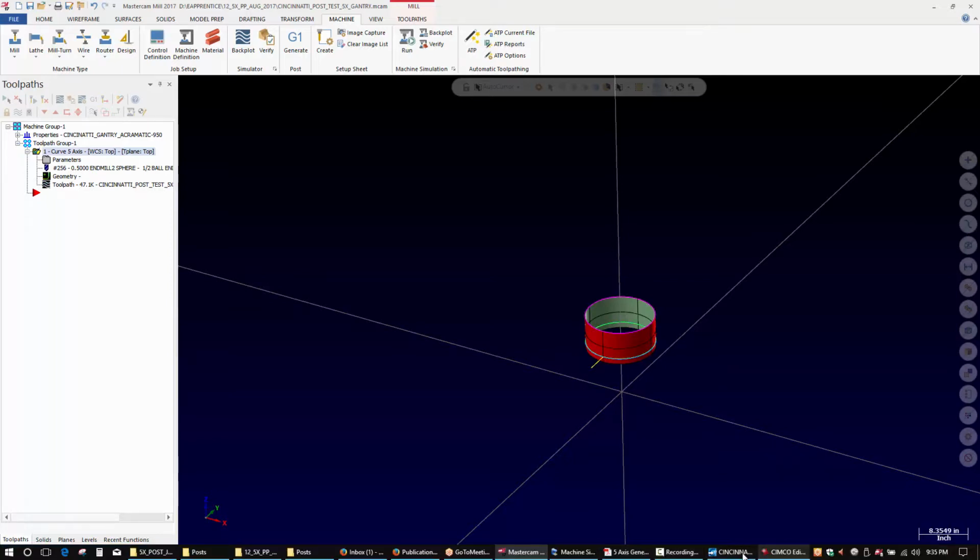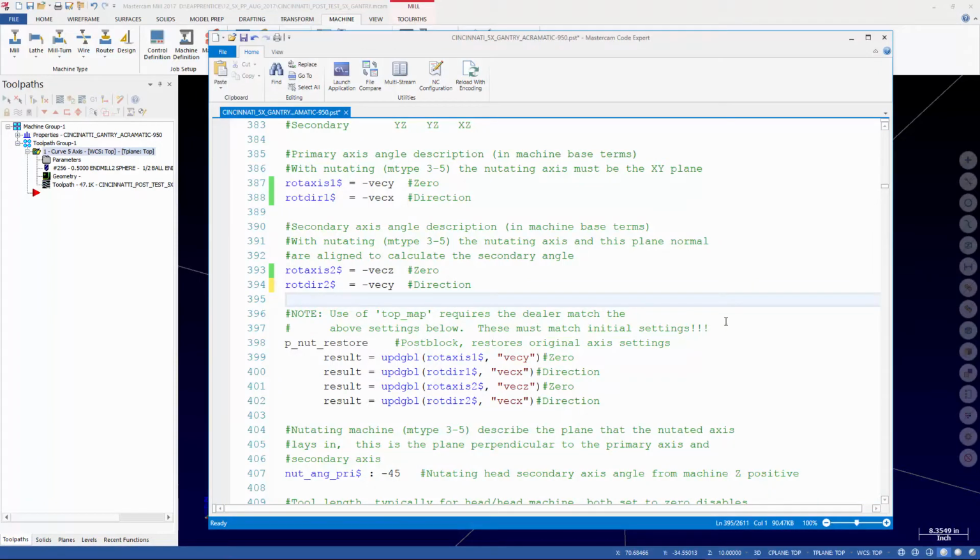So Jeremy's saying, vec y rotates around x. Vec z and vec y. You have to have the two perpendicular vectors. So this is the 0 point, which means my tool axis vector is pointing straight down, which is true, right? So at A0, my tool's pointing straight down.